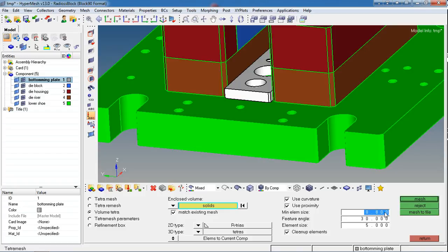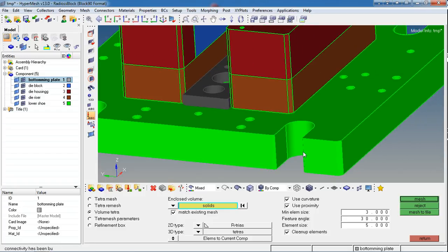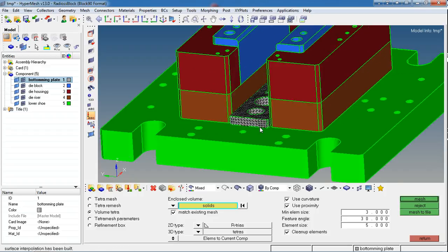This is also not recommended because the element size greatly affects the performance and accuracy of the output. Of course it also increases the solving time, but as I said, for demonstration purpose I'll be quick and fast. That's why I'll be keeping this bigger.